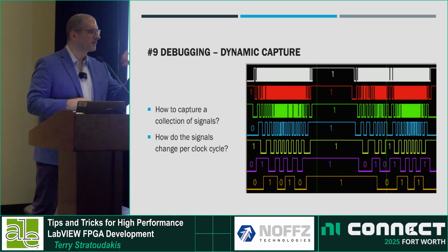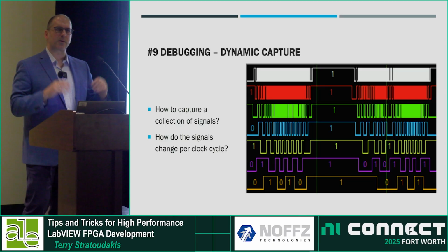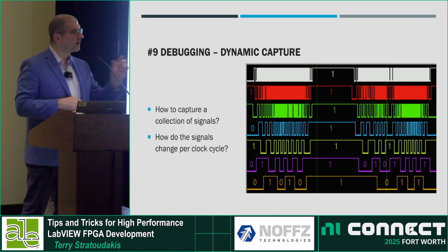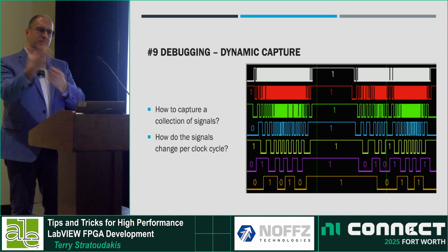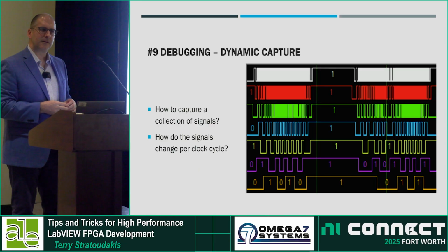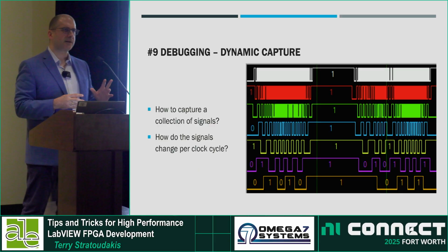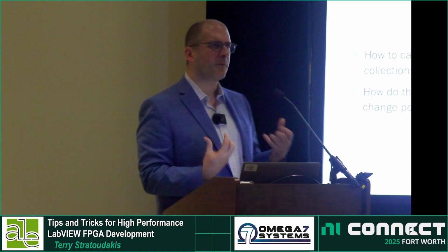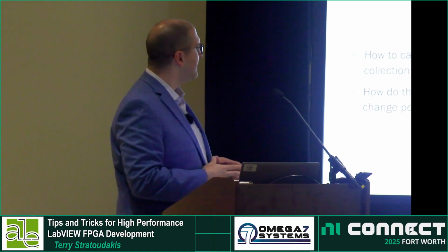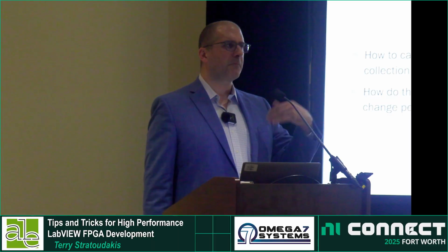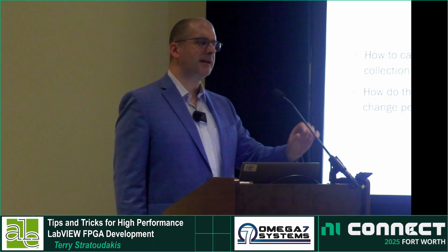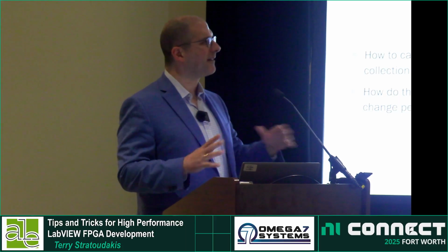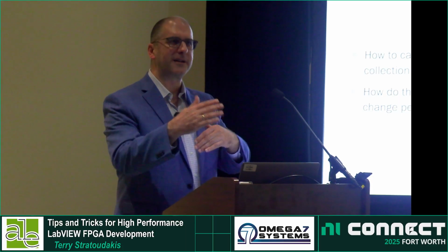In the AMD Xilinx Vivado world, they have something called the Integrated Logic Analyzer, ILA. It's a block you can put into Vivado, and it allows you to capture data and do this exact same thing. A common request, whether from LabVIEW users or from the Vivado side, is, hey, I really want an ILA in LabVIEW FPGA. You can't use that block directly because it needs JTAG, and there are some other things that make it unavailable to us. That's the bottom line.